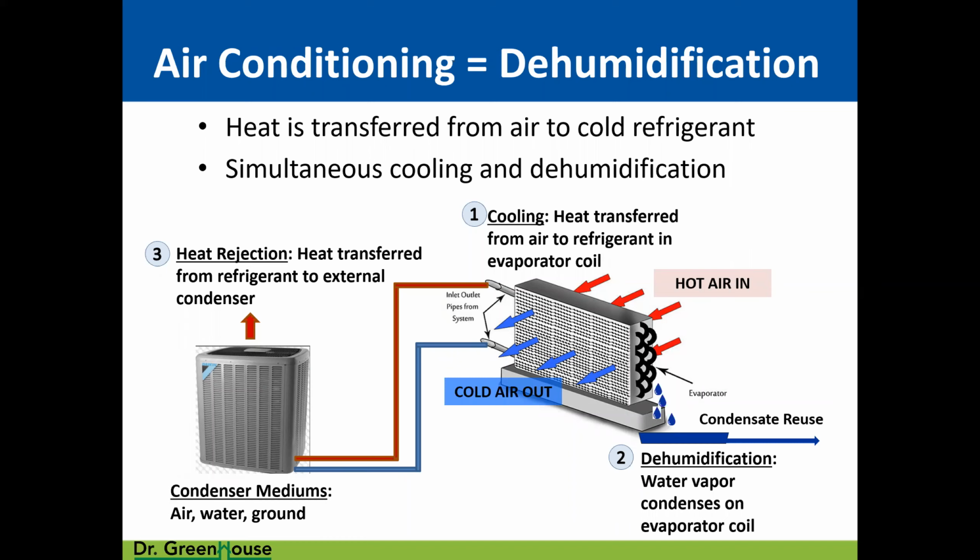The reason that's happening is that the air conditioner is being activated to condense out the moisture that's being recirculated from your car. And then there's a heater after that that reheats that air before it gets delivered through the vents in your dashboard.